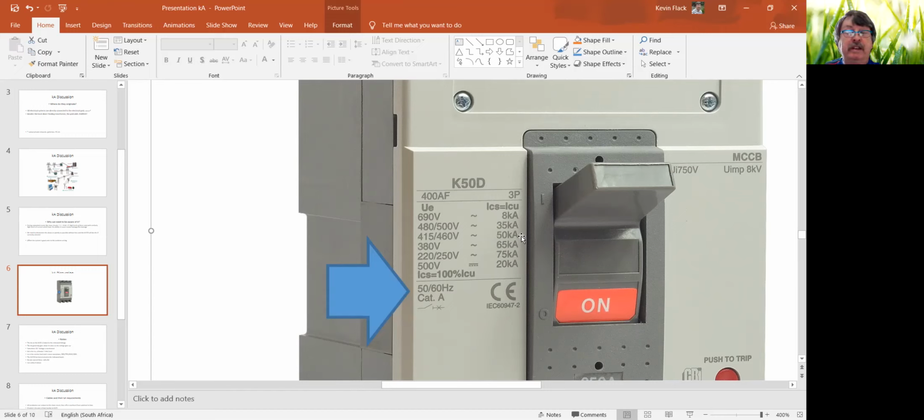The reality is that in our houses, for instance, we might in 20 years have 20, 30, 50, 60, 100 operations and the breaker doesn't break. So why would that last so long? That's lasting so long because the prospective short circuit of these specific faults that are being experienced are far, far less than what we have from a breaker design perspective.